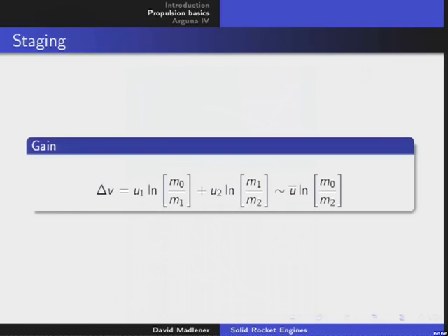So the problem is that normal rockets have an exhaust velocity only in the order of 1 to 4 kilometers per second. So how do you achieve 10 kilometers per second or more? Well, this rocket, for example, has an exhaust velocity of 1.7 kilometers per second, and it would never be able to achieve higher velocities. If we have a mass ratio of about 3, then you get an ln of approximately 1, and you would achieve exactly 1.7 kilometers per second. But again, there's air, so you normally get to maybe 1 kilometer per second.